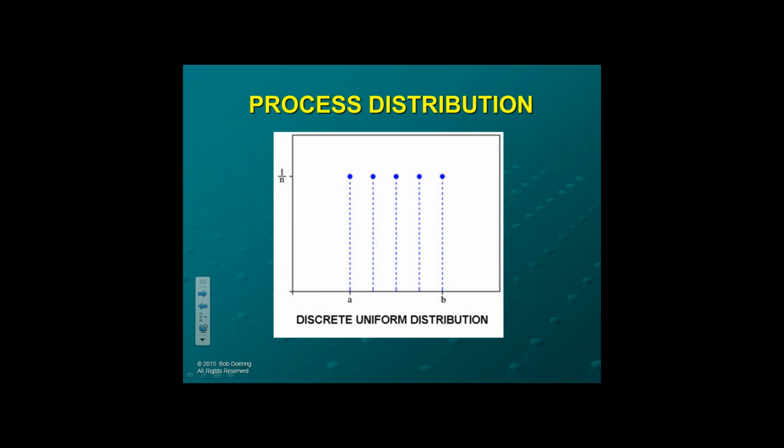Now some people say, well, you know, we don't believe anything unless we see a journal article, so okay, fine. Here's a journal article called Process Control and Evaluation in the Presence of Systemic Assignable Cause. This was printed back in 1997, and of course, they call it an assignable cause. It's incorrectly identified as much, but let's see what they came up with. In this journal article, they took 50 consecutive pieces and collected them from a bar grinding process. They were measured over a cycle and measured for the diameter. And what they discovered was, in the grinding operation, over time, the dimension gets larger.